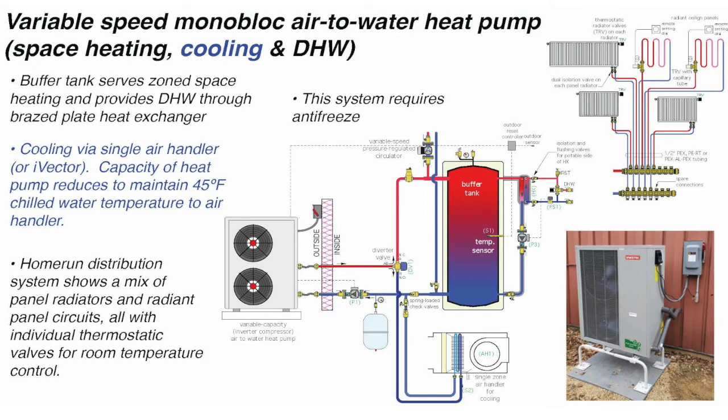Well, we're doing it with that external brazed plate heat exchanger. This is a detail that is used in Europe quite a bit, yet we don't see it used over here. And we've designed systems around this, and it works. It's a stainless steel brazed plate heat exchanger. I'm sure many of you have worked with them. And it can be set up on a flow switch.